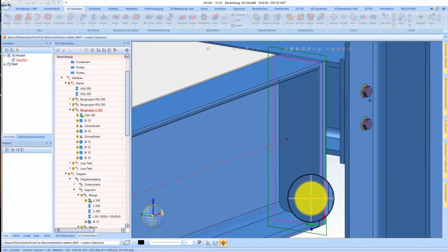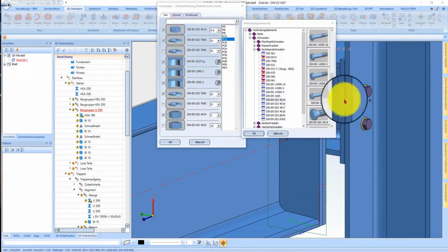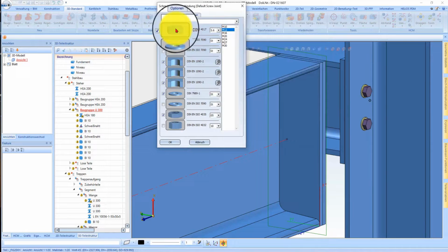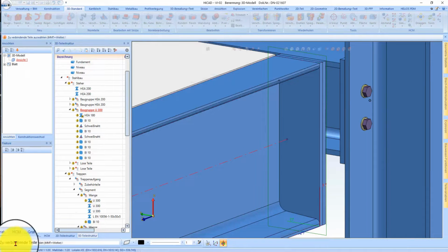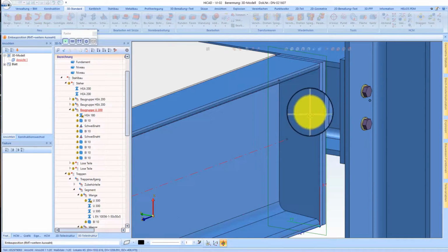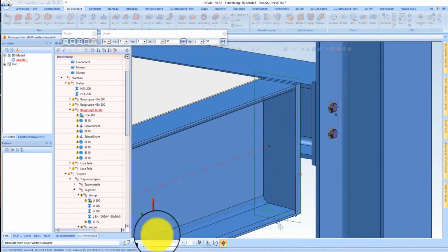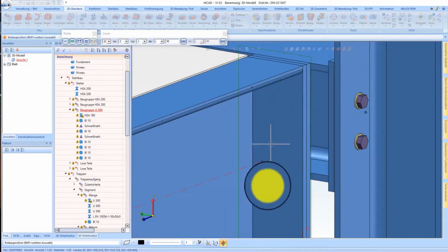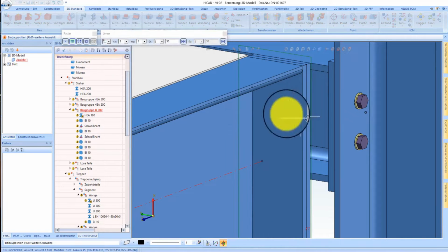Then I set the plane. I want to have my plane here, and I select my screwing here. Like this, for example. And yes, indeed, leave this screwing. I want to screw this plate to the other plate with a mouse click, then continue. Now I have a screw here. I would like to make it vertical, so let's just use 2 screws. That means I want 1 in the Y direction and 2 in the X direction. Of course I also have the option to define the insertion point here.